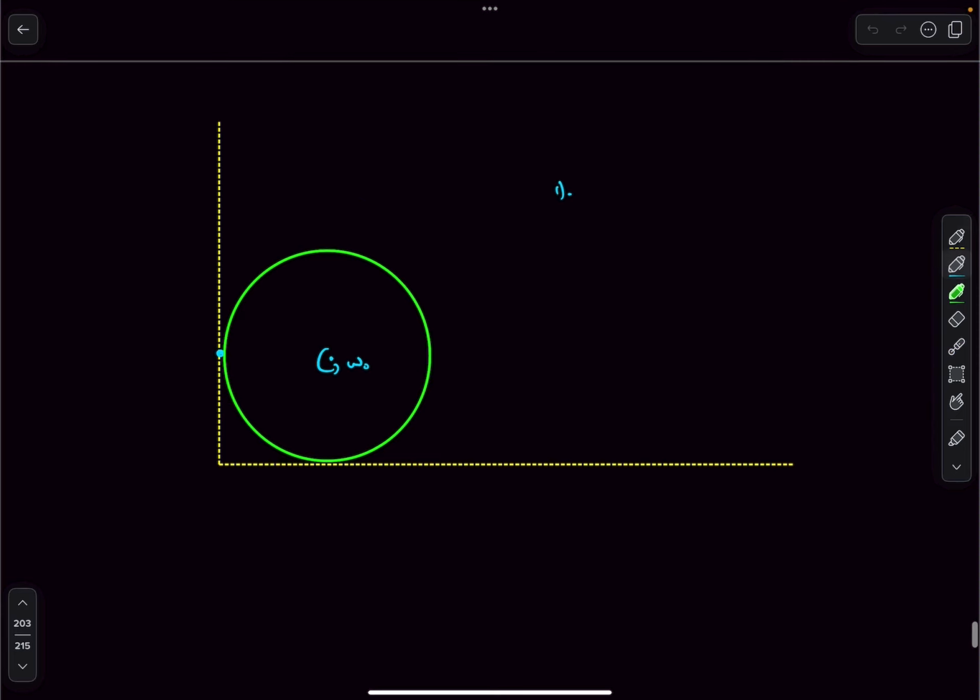Okay guys, firstly here we'll work with the assumption that the center of mass remains in its place. Basically the cylinder is not moving horizontally. In this case, the point of the cylinder in contact with the left vertical wall is slipping in the downward direction, right? Because omega is in the counterclockwise sense, this point will slip downward. So the kinetic friction force on the cylinder will be vertically upward, which I'm going to call F1, and the normal reaction applied by the surface as N1.